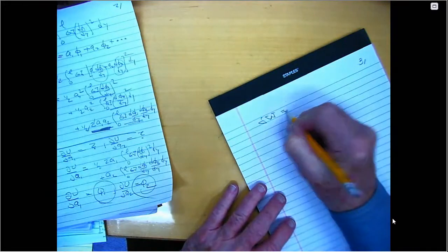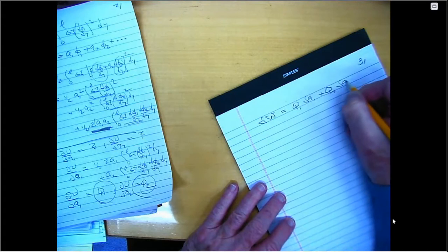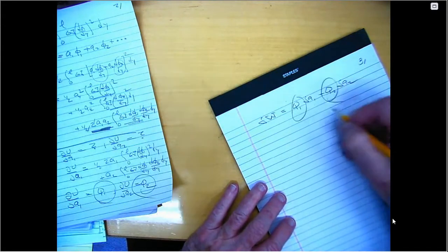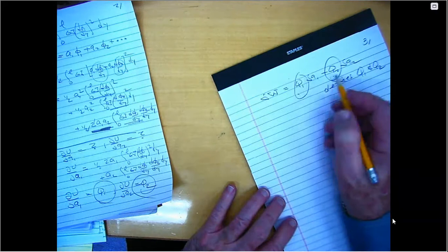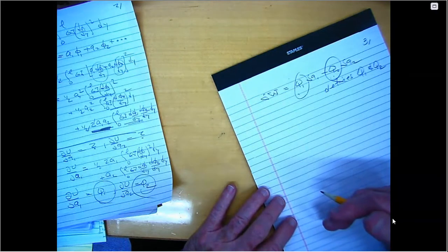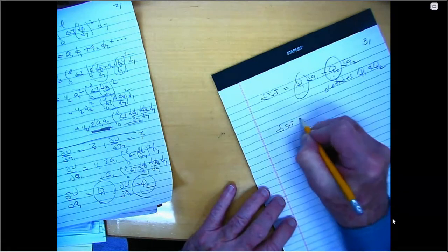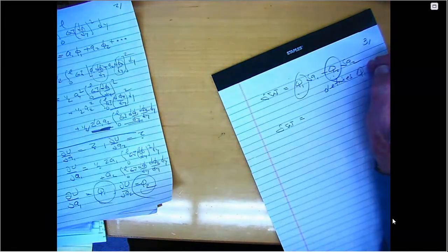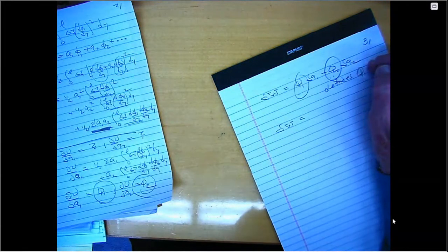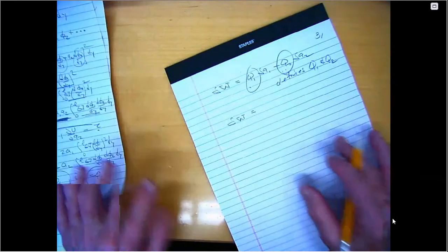Well, del W, by definition, is Q1 del A1 plus Q2 times del A2. This really defines Q1 and Q2. So, to find those things, I need separately to write down another expression for del W. And I start with physical reasoning. In this particular case, I mean, this is true forevermore for all of eternity, according to Lagrange. But for any particular case, I need to be able to write down the virtual work expression for my system.